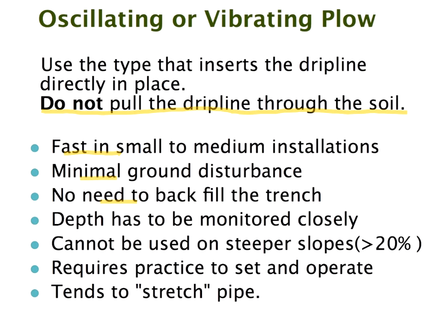You have very minimum ground disturbance. You don't have to backfill the trench. You have to watch your depth because as the plow bucks, as you go over uneven ground, the rear end can jump up and down a little more than you want it to. It's pretty hard to use on a steep slope because you're putting it on the contour and it's going to roll over if you're on a steep slope.